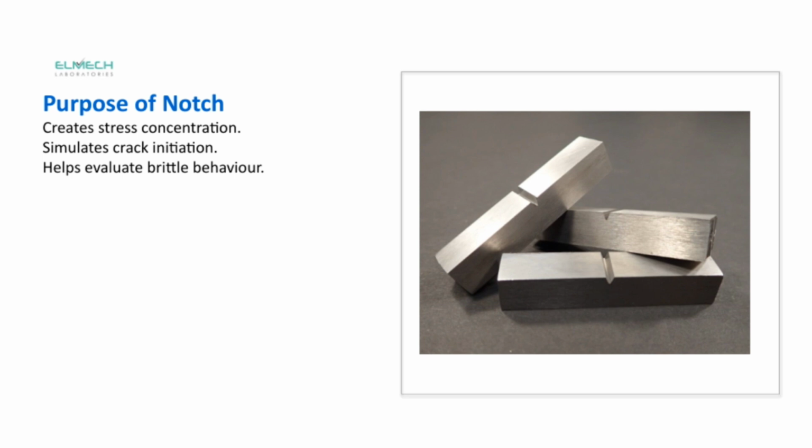This is particularly useful because it helps us evaluate how materials behave when they are brittle. Brittle materials tend to fracture suddenly, so understanding where and how cracks start is crucial. Overall, the notch is a simple but powerful tool that allows us to better predict and analyze material failure, linking directly to our goal of improving material reliability and safety.